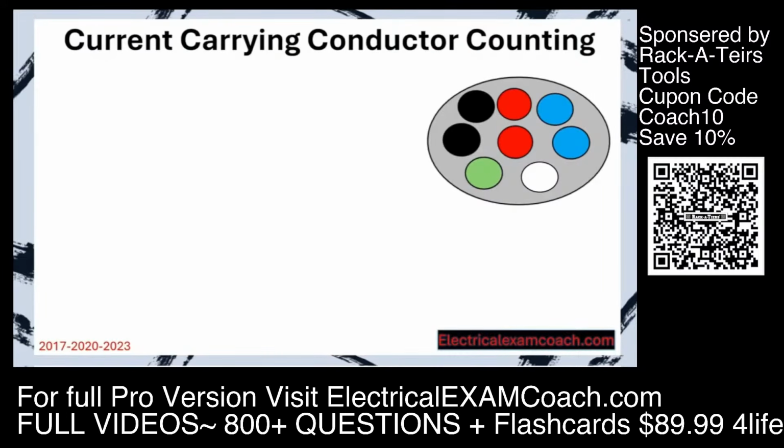You may get a question on your exam that gives you the number of conductors. That's easy. You're going to go to the tables and do the math. But you may get a question on your exam that asks you, in a scenario of wires, how many of them are current carrying conductors? The first one's easy. All ungrounded conductors. All of the hots are going to be considered current carrying conductors under normal circumstances.